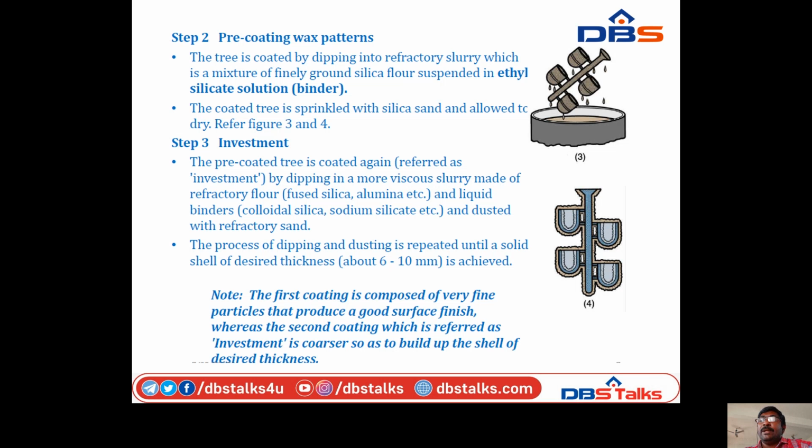The process of dipping and dusting is repeated until a solid shell of desired thickness, about 6 to 10 mm, is achieved.